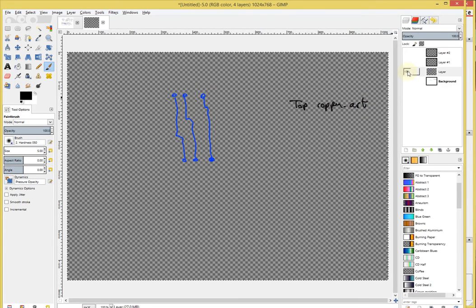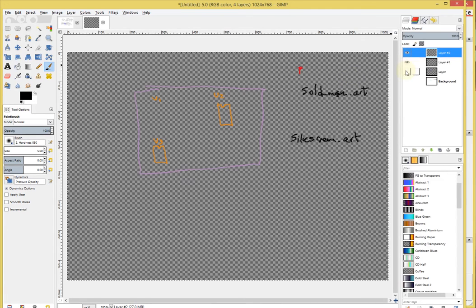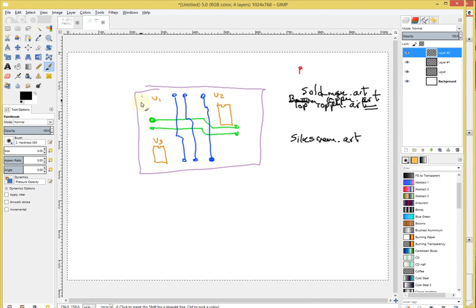Art. And then I turn all the visible features of that layer off, and then I turn another layer on. So this could be the solder mask layer, right? And I generate a solder mask Gerber file. Then I turn everything off in the color dialog, and then I turn specific features on that are specific to the reference designators, and then I generate another one and call it the silkscreen for the top. Right, so each particular layer will have its own file, and the composition of all these layers is that we have the complete board specification.